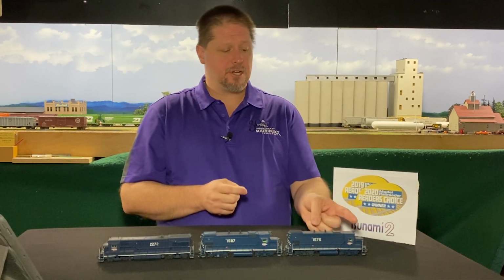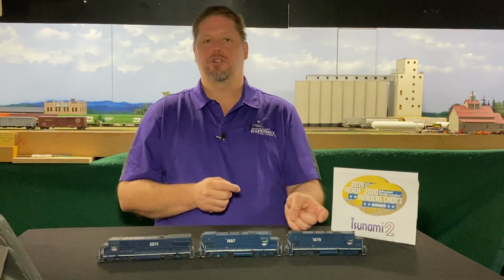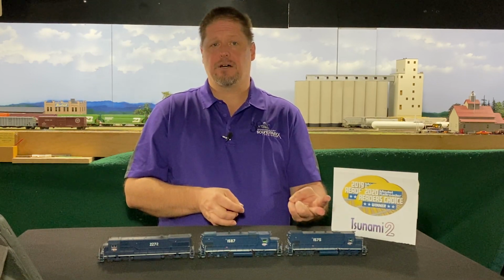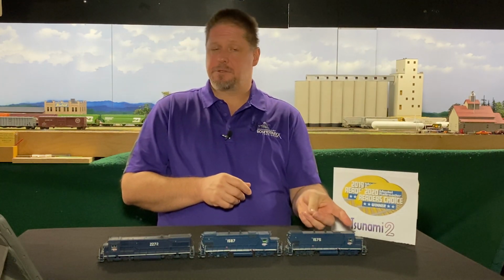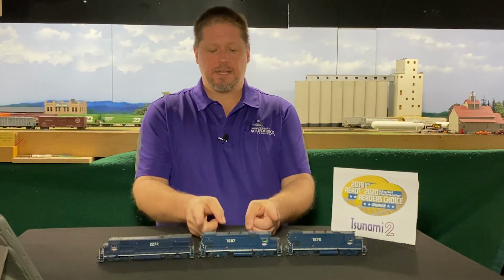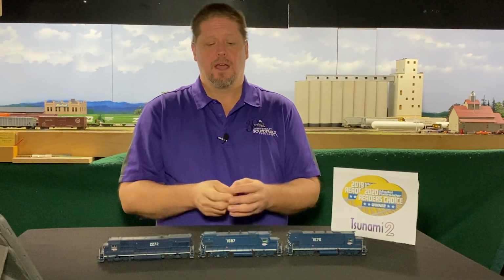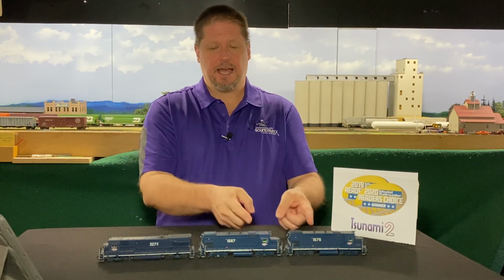So moving forward, speed step 10, number 1575 says, yes, I'm supposed to move forward, speed step 10. Now it says F0 being the headlight, yes, I'm supposed to turn that on. F1 for the bell, yes, I'm supposed to turn that on. F4, let's assume it has dynamic brakes. Yes, I'm supposed to turn that on, and then does so accordingly.